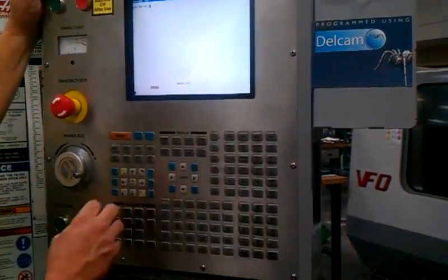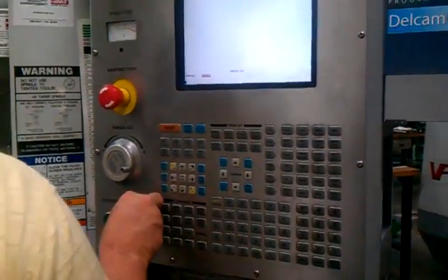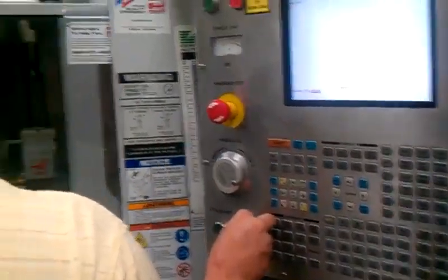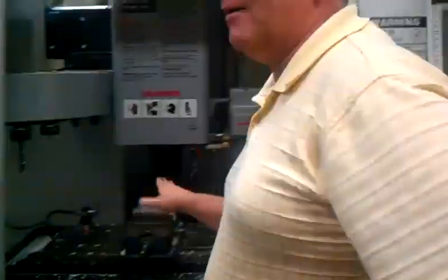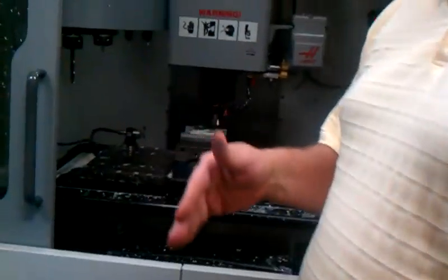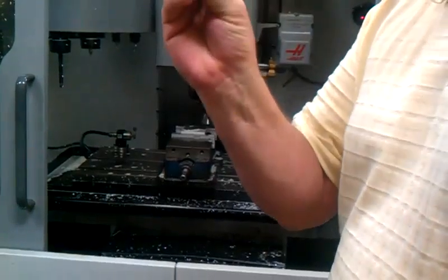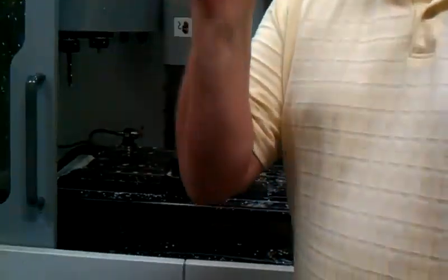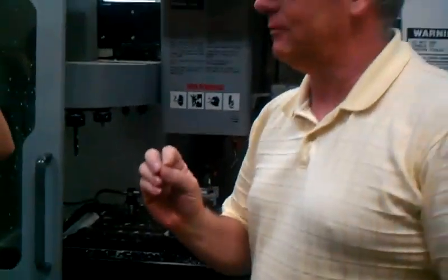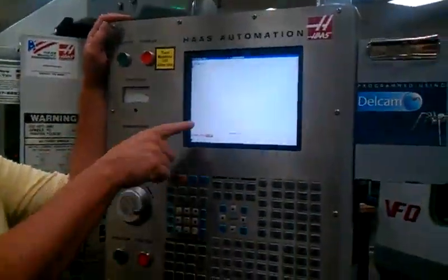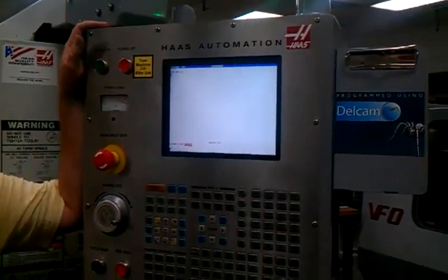End of block insert, cycle start, comes down to 1 inch above my part program 0 and Z. I sent it to 1 inch with height offset number 1 active. You like? Does seeing it help a little bit? Oh, yeah. If we were to look, guys, I sent it to 1 inch positive.